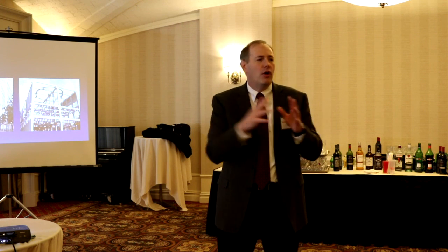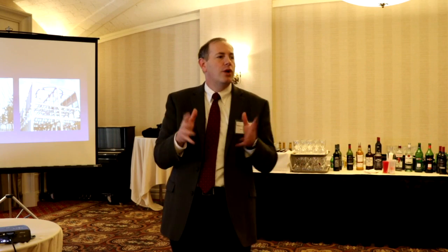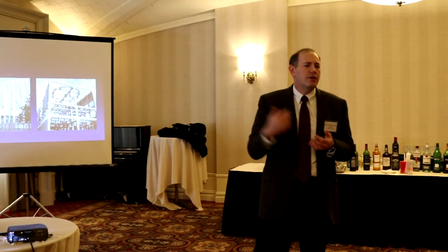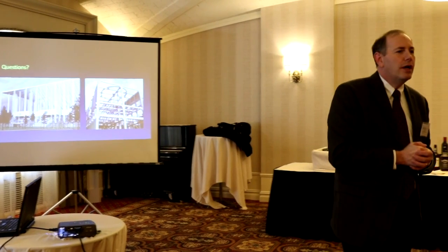We outlined, looking at every single thing, from bond to shear strength to cracking, all types of things, what needs to be done to move to the higher strength bars. I saw Ramon, he was involved in that effort too. It was kind of interesting because when we were doing that study, my student was still working on this. I said, hey, everything was grade 60, let's just throw in 100. So in his dissertation report, we had a little look at what needed to adjust, and just a few little things would adjust, but in general, what we have works for grade 100.